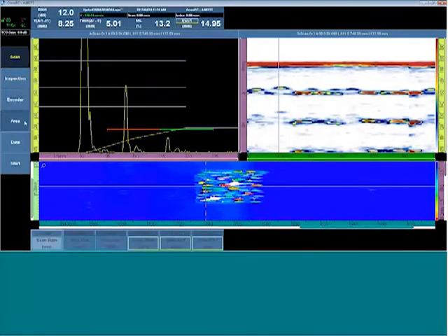In a one-line scan, we only saw available the configuration for the scan axes start, end, and resolution. Now that we've switched to a two-axis inspection, also now available is the index, which again is the green side, for the start, end, and index resolution. So we would build the C-scan one part at a time, one stroke at a time, continuously.